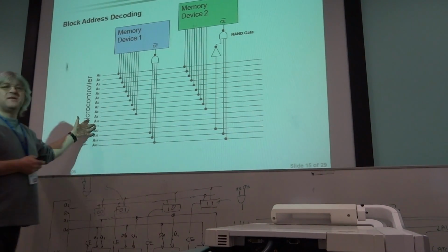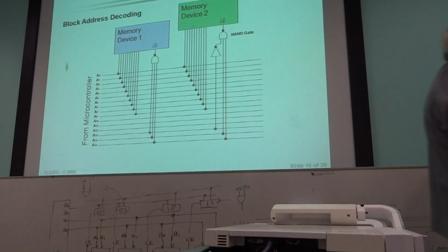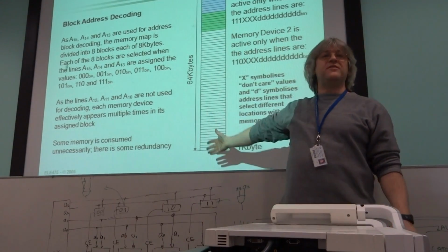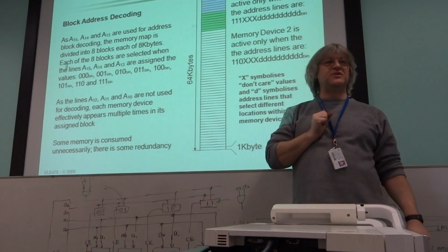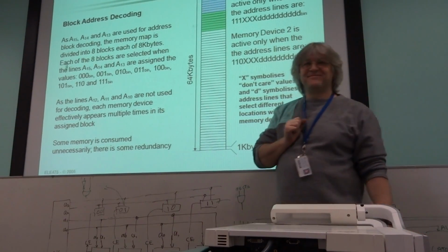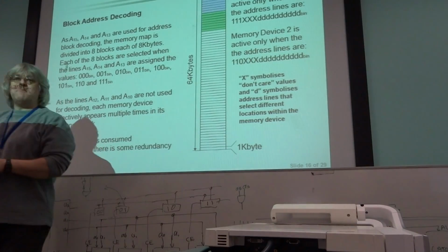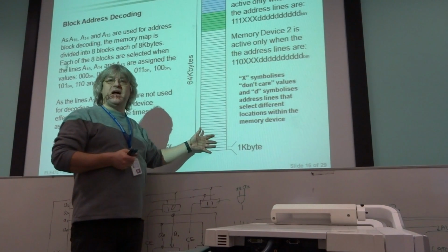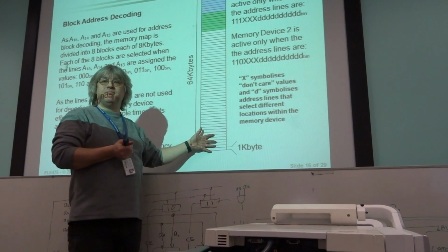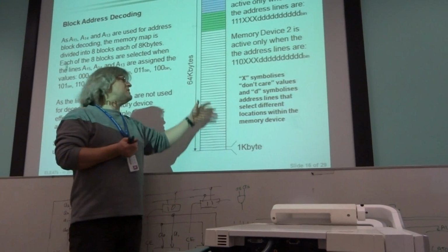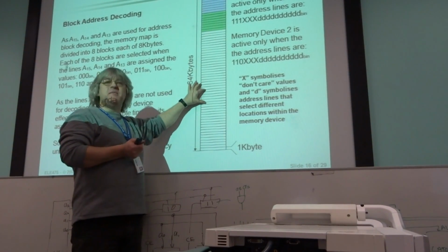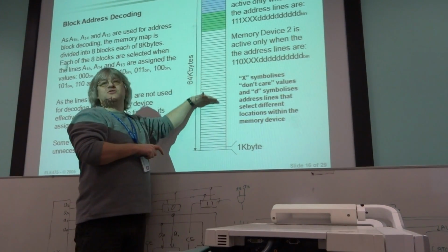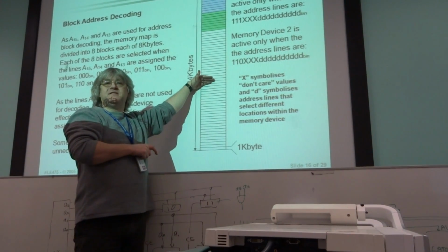If we look at what happens with the memory map with this combination, you'll see that we get aliases, but we don't get aliases throughout the whole of the memory map. We only get it confined to a specific region. Now you might say, well, who cares? It means that I can connect additional devices, and provided they sit elsewhere in this memory map, that's fine, it's not a problem. What I have to do is to make them sit in a particular place in the memory map, and provide the appropriate address decoding so that they'll be awake when addresses within that range are activated.